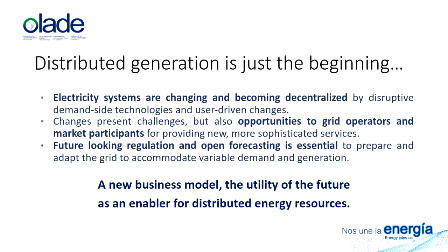And actually, if you look at that research from Hawaii, there's circuits where they have about 60% penetration, which is massive. And even with these functions, they have seen that this self-curtailment of solar inverters was only active for about 1 to 2% of the time.